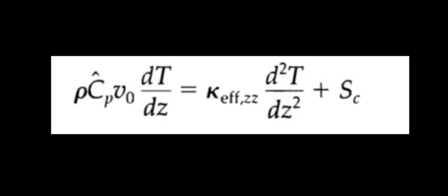The effective thermal conductivity Ke is not simply the thermal conductivity of the fluid but accounts for heat transfer through both the fluid and the solid particles in the packed bed, as well as the mixing and dispersion effects within the bed. It is a crucial parameter that can vary between the inert and the catalytic zones due to the potential differences in packing and flow characteristics.